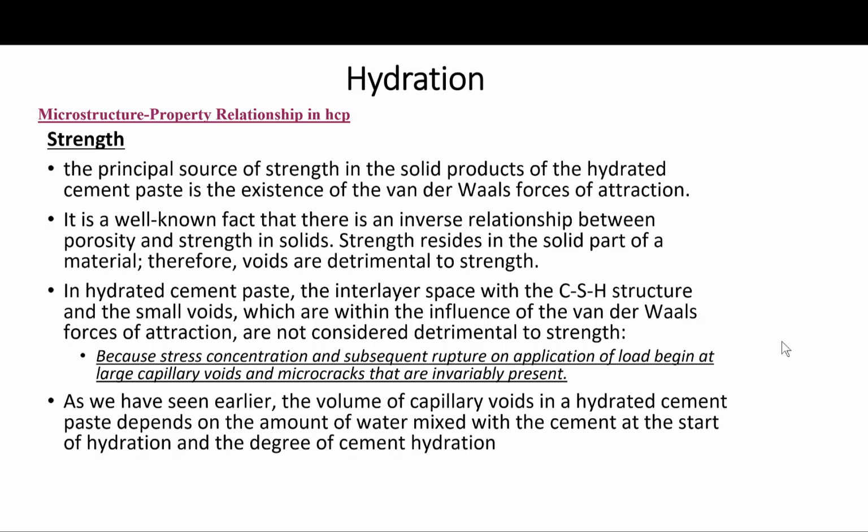This is because the stress concentration and subsequent rupture on application of load begin typically at the large capillary voids and the microcracks that are invariably present within the paste. As stated earlier, the volume of capillary voids in hydrated cement paste depends on the amount of water mixed with the cement at the start of the hydration and the degree of cement hydration. Okay?